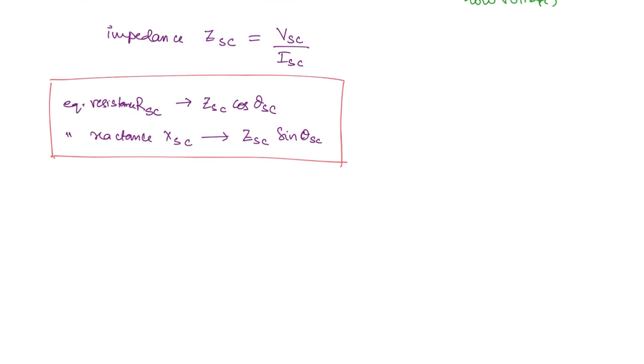So here also there are a few points that you have to remember while performing the SC test. The test should be performed at rated current condition. And the second point is, like I have already mentioned, this test is performed on the HV side. HV side is energized. Note that this is only a preference. It is not like if you do it on the LV side you will not get the result, but it is preferred to be done on the HV side.